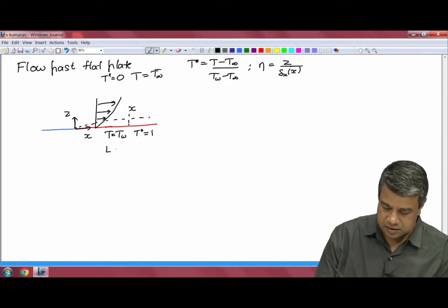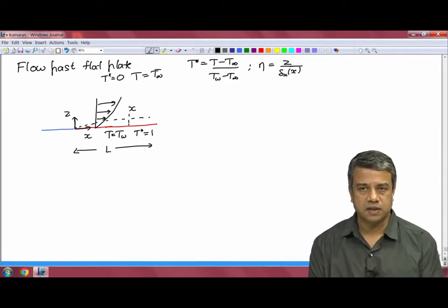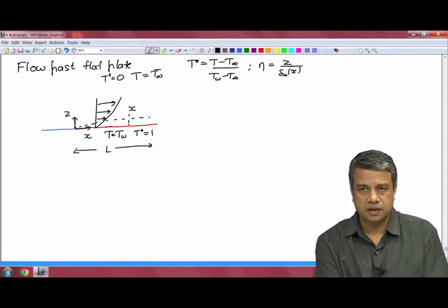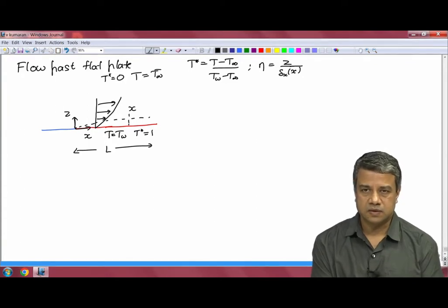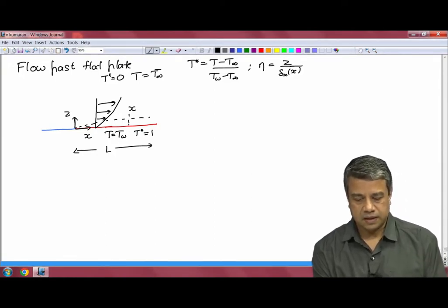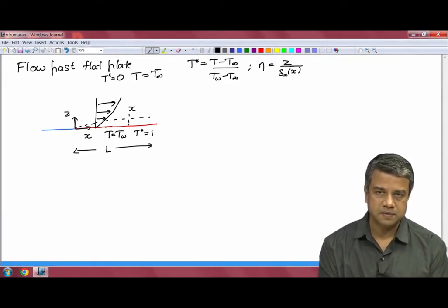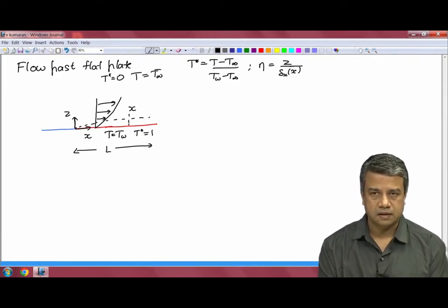And the reason is because in the limit of high Peclet number, we can neglect streamwise diffusion in comparison to cross stream diffusion. Convection transports heat downstream, and diffusion is perpendicular to the flow direction, and therefore the total length cannot affect the temperature field at a location that is upstream of the end of the heated plate. Because of that, the local temperature depends only upon the boundary layer thickness, which is a function of x from the start of the heating section.